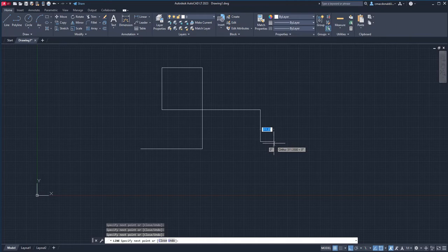Ortho Mode is very, very easy to access. If you want to move towards Ortho Mode, you just left click, and if you want to turn it off, you simply left click and you can reselect polar tracking. Another particularly useful tool for drawing is the dynamic input tool.